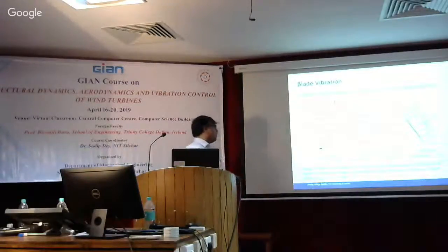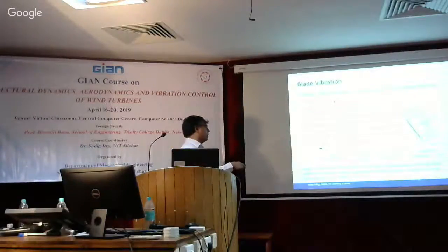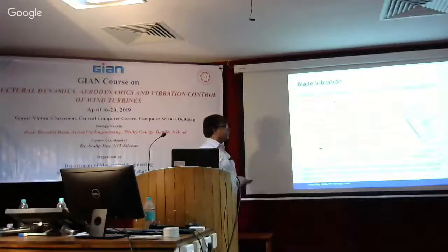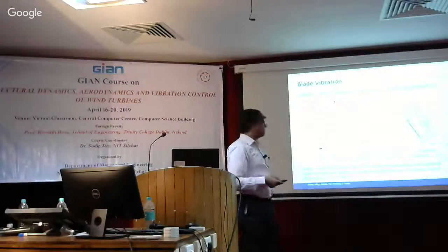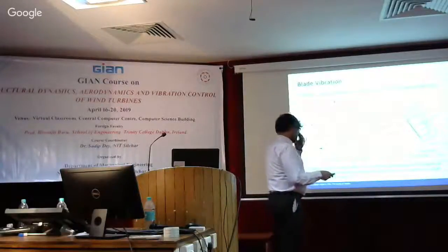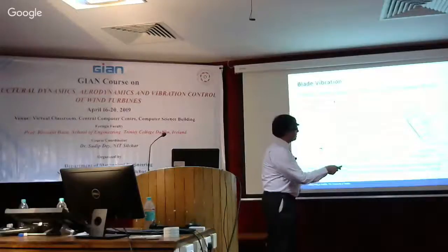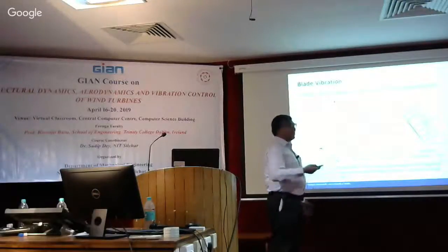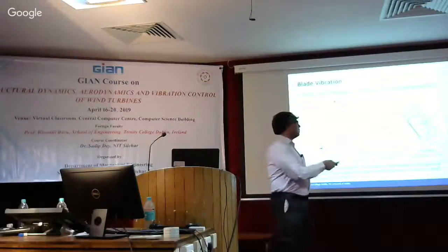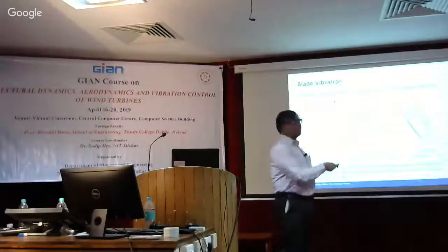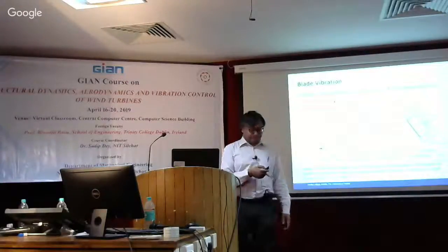And if you look at this paper, Structural Control and Health Monitoring, you can get the details on this. And I think somebody was asking about the centrifugal acceleration, right? So this is of the order of 7 to 9 G. So as pointed out, the liquid is normally in this position. So that's exactly ideal, because this is where we want it to be, so it can move through this orifice and dissipate the energy.